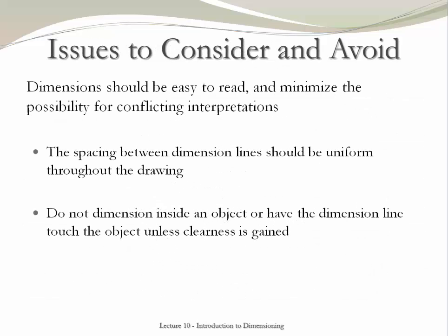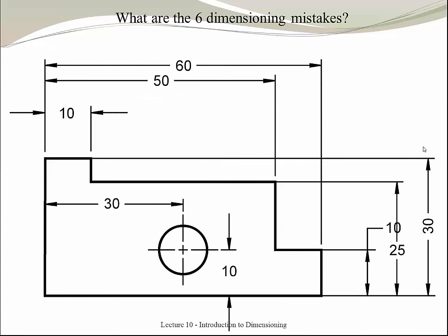Let's now go over some of the issues you need to avoid when creating a drawing. In general, keep in mind that the drawing must be clear and easy to read. Here are some suggestions. Avoid conflicts, maintain some space between the dimensions, and do not use dimensions inside of the object. Let's do an example.